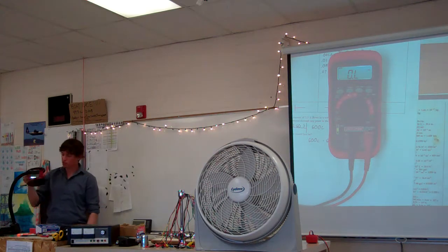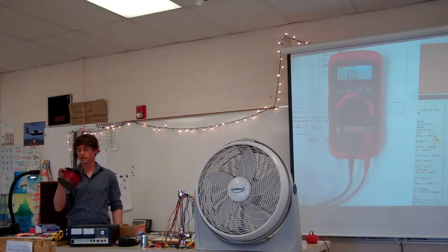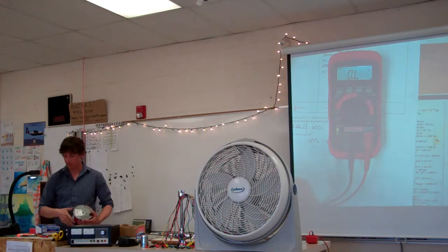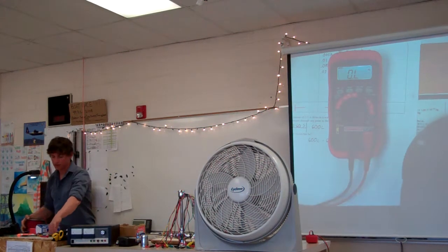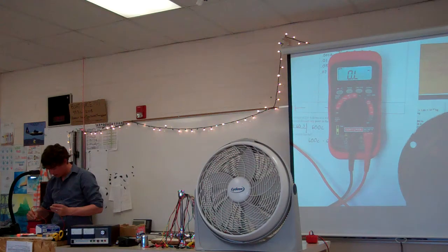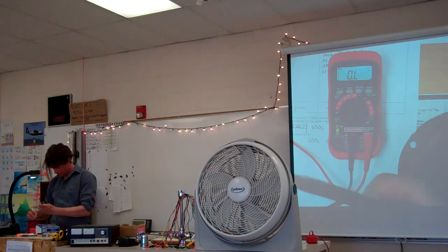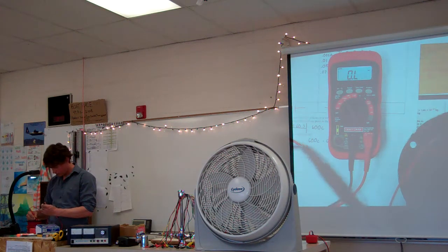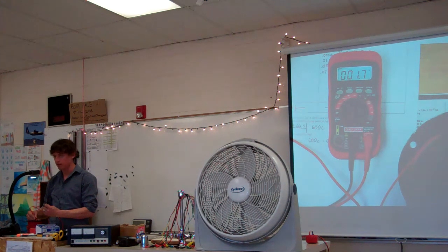Okay, let's see. I got an entire spool of wire. It says it's 500 feet, but we've used some, so it's not actually 500 feet. You can measure the resistance of the whole thing by connecting right there and then to the end. It'd be higher than the shorter piece of wire. Okay, what do we get? Look at that, low, 1.7 ohms for that whole wire.